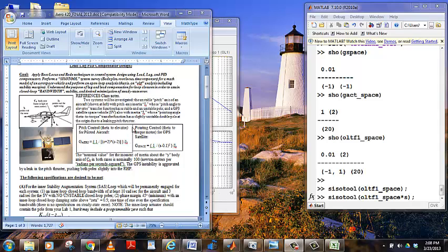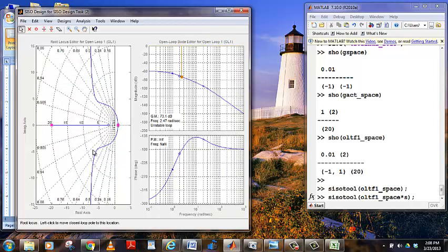Okay, this is the space problem that we're talking about here, where the poles are slightly in the right half plane and there's a nominal value of 100 for the pitching. We want to pitch this spacecraft, this GPS satellite, to keep it pointed towards the Earth. As with the aircraft case, I have these two unstable poles shown here in MATLAB. If I put in an actuator with a programmable zero at 2, so I have (s+2)/(s+20), I'll have an open loop system as shown here.